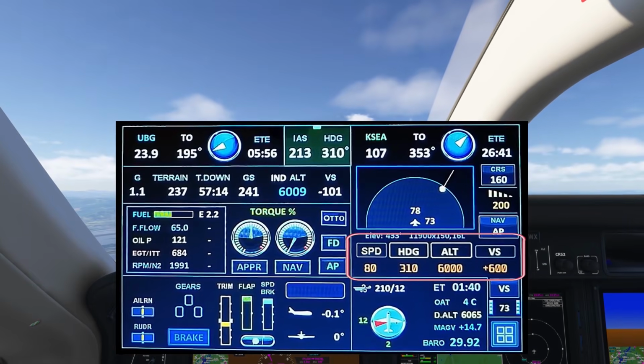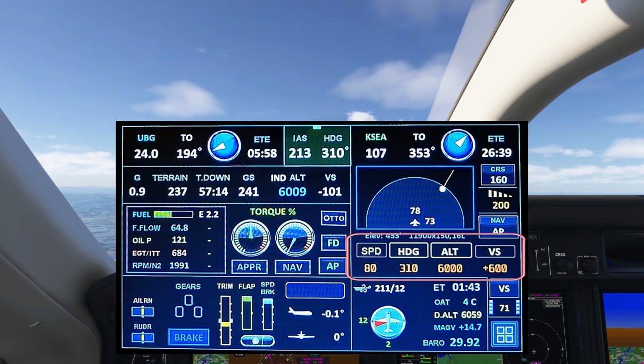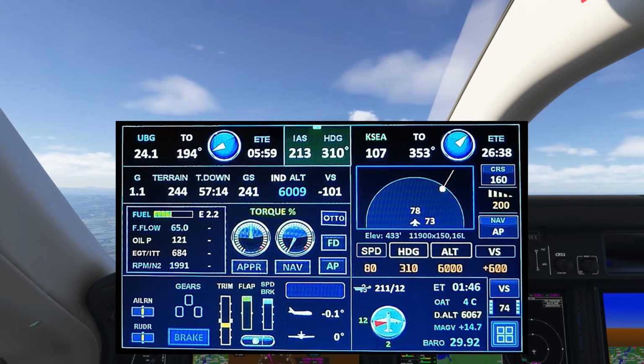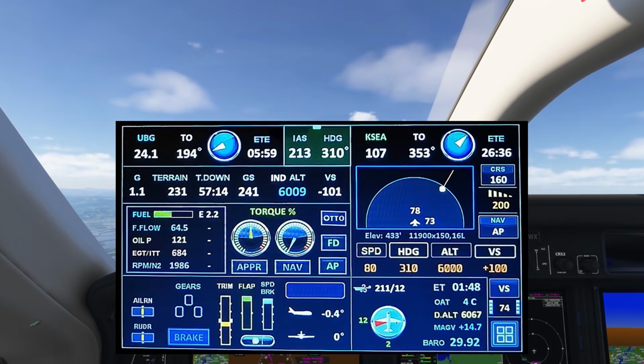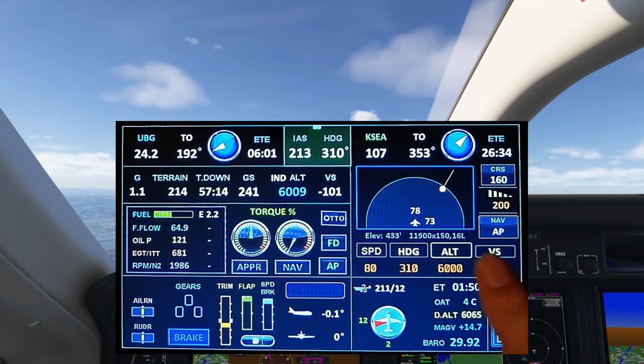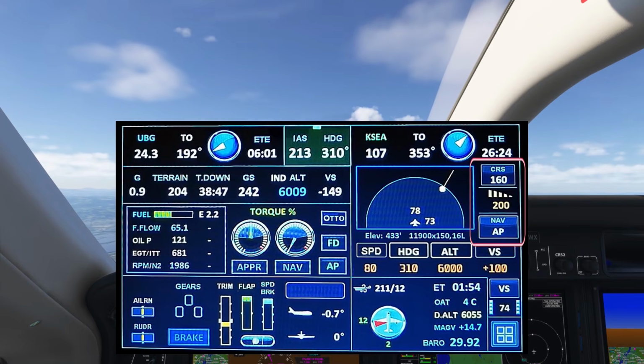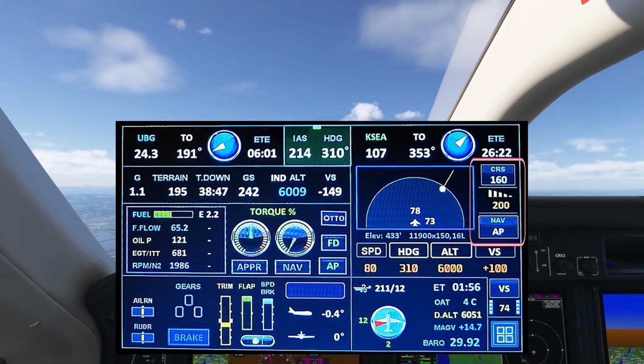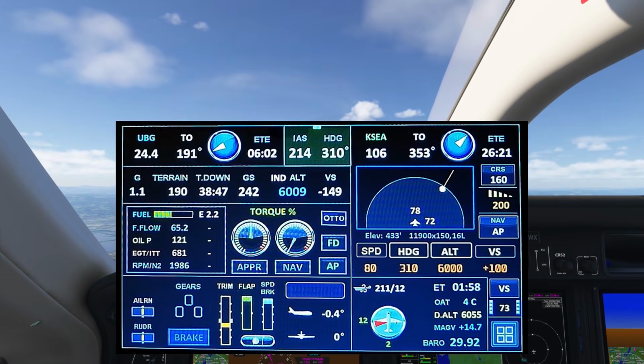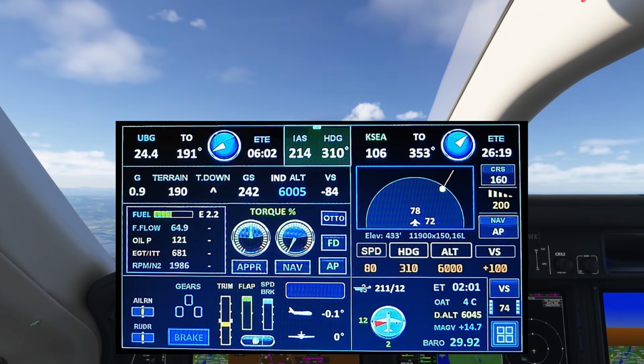Right below, you have access to the basic autopilot settings, which you can see and modify right from here. A reason why the autopilot is grouped with the navigation display is that you can actually couple the autopilot to the ESP panel to let the logic in the ESP fly the airplane right onto the final approach.